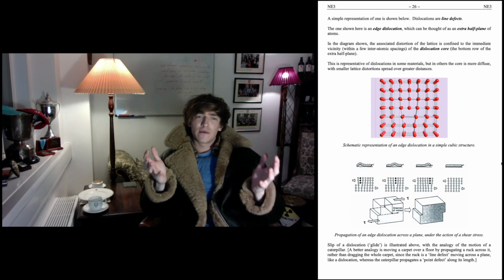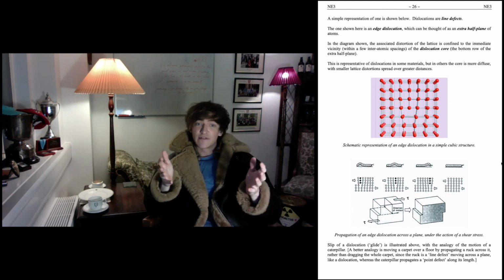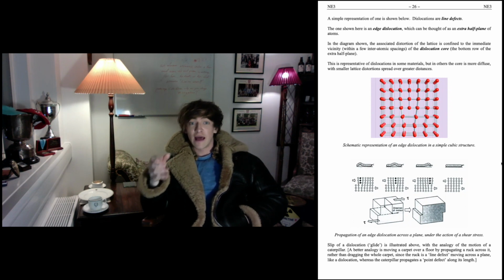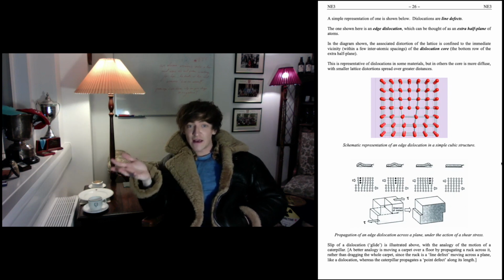But what about the magnitude of the displacement that's generated? For that, we have a Burgers vector. That's our next bit of materials vocabulary we need to understand. The Burgers vector gives both magnitude and direction. And that can be obtained by tracing the path around the dislocation which closes. Should there be a closure failure in a perfect crystal, the magnitude and direction of this closure failure defines the Burgers vector.